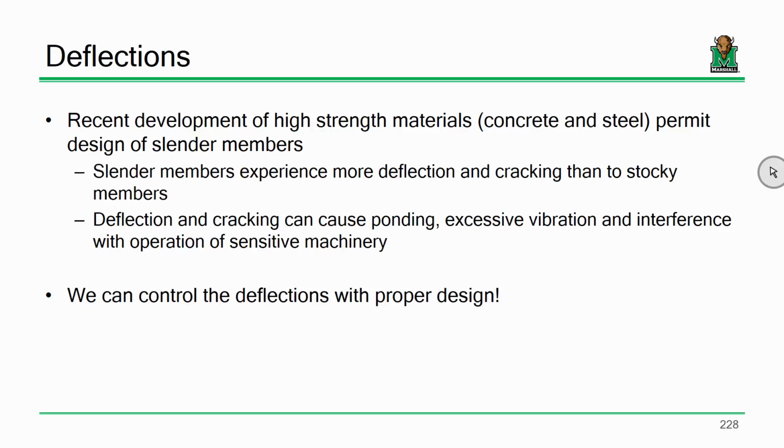And the main idea behind service limit states is because we're dealing in a world where we've got high strength materials and more economical ways to design. We can design fairly slender elements that can resist these loads safely, but the problem is when a member gets too slender, it deflects too much, and it's more than just safety that a structural engineer needs to provide.